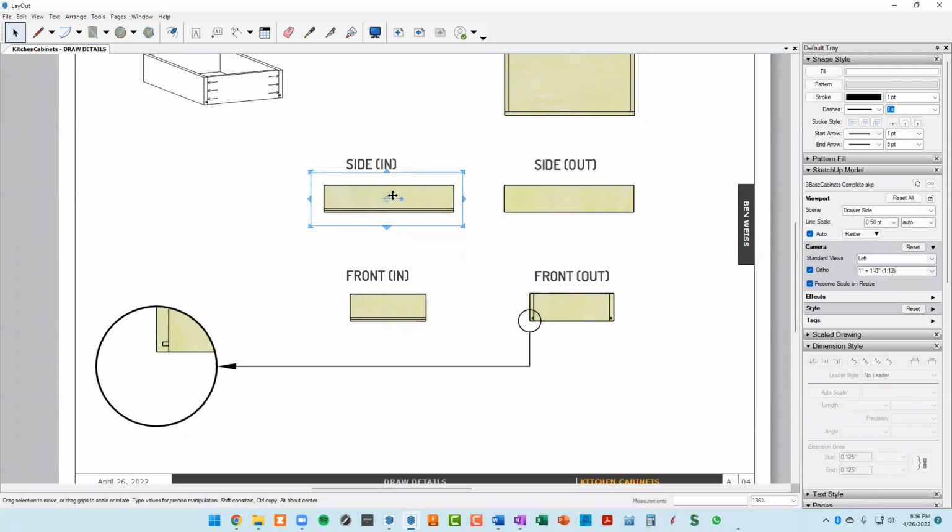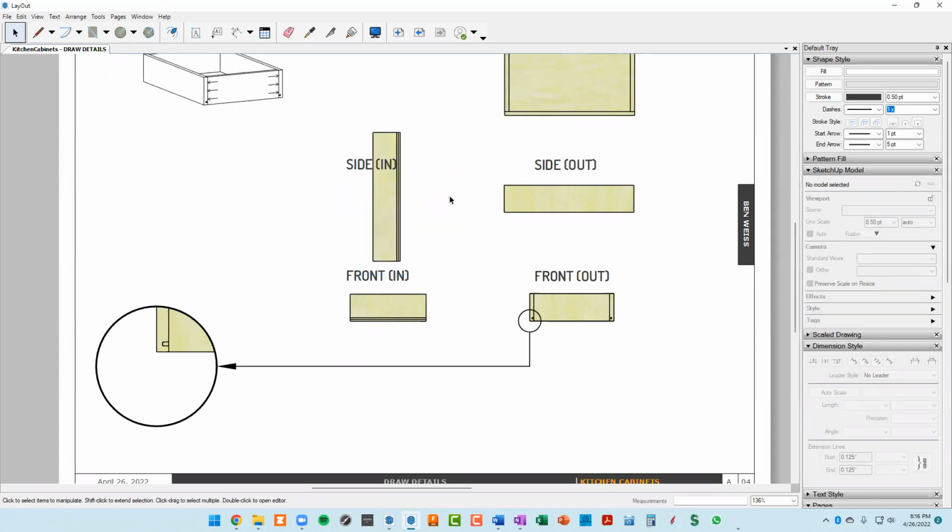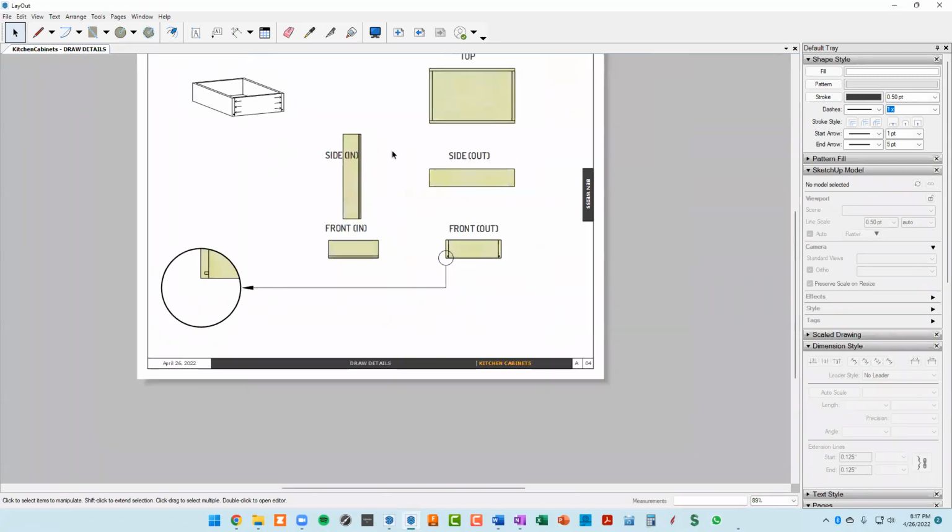So I guess you could take that approach because you can also rotate these things. So you could do something like that where you show individual parts and then just rotate them within layout to kind of simulate that exploded view. But again, no automated way, unless there may be a plugin that does it in an automated way. But I have not seen that.